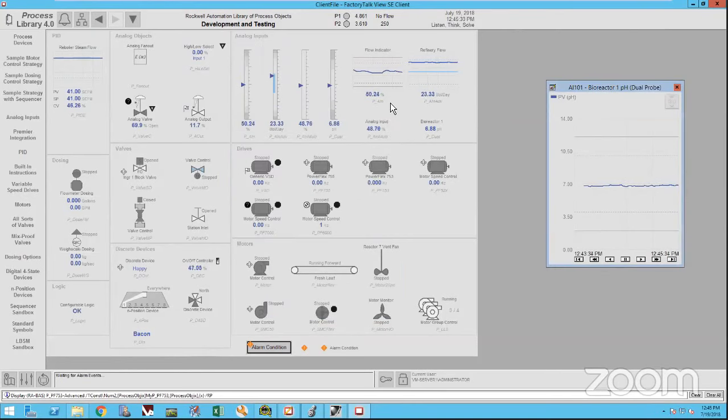So this is showing you the analog inputs. All of these are essentially, this one here and this one here are the exact same point. So this gives you an option on the screen when you're doing your P&ID layout of how you want the operators to interface with this. Do you want them to see a little 2-minute window of what's been going on, so they know if it's a straight line up, if there's an issue? Or do you just want to see the little bar graph to see where you are? There is a shading setting on there so that you can see when something is changing. So over the last 8-hour shift, you can see where your analog has been up and down. All of that's already pre-built into it.